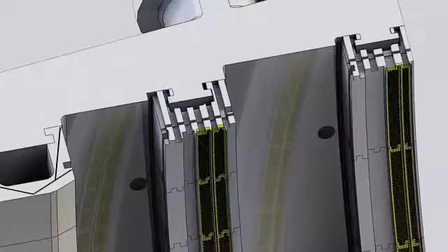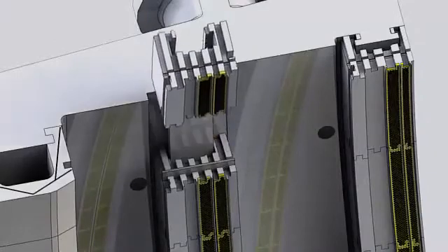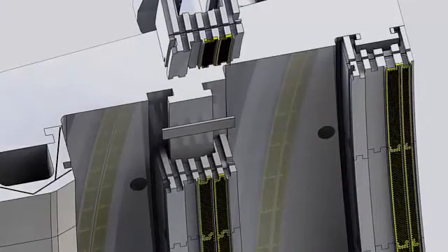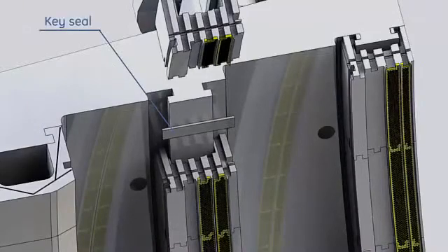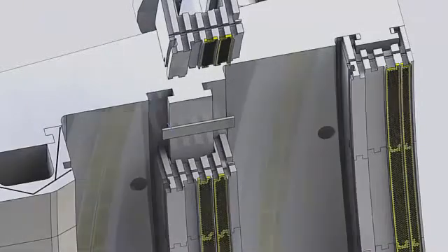This honeycomb is relatively soft material. The cutter teeth on the tip of the second and the third stage buckets open a slot on the honeycomb seal without any material transferred, providing tighter clearances to improve the unit efficiency. Shrouds of the last two stages are sealed by interconnecting tongues and grooves and by key seals.